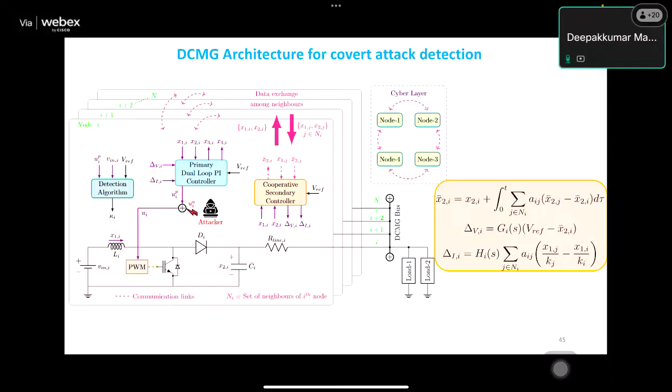So we are talking about UIA, and coming from the control is UIP. The superscript is used here, and the total signal is nothing but UI, which is the addition of two signals, UIA and UIP. Right? And the PWM signal will go to here. It will remain the same because it doesn't know that part of the control is coming from the attacker and part of the control is coming from UIP. UIP is modifying depending on what the attacker is injecting. So therefore UI doesn't have any way, you can't detect this kind of attack.